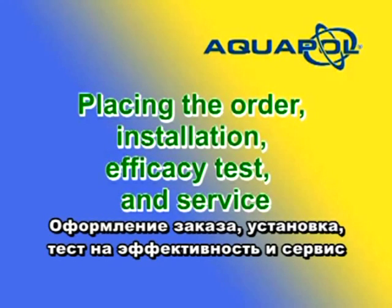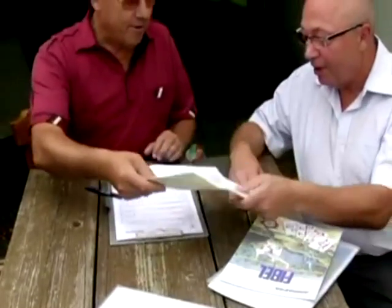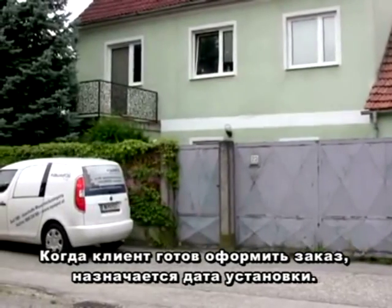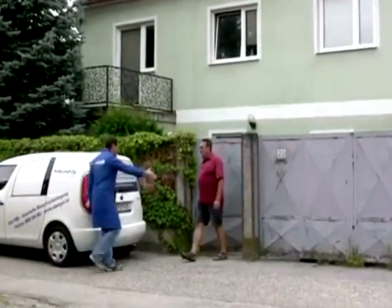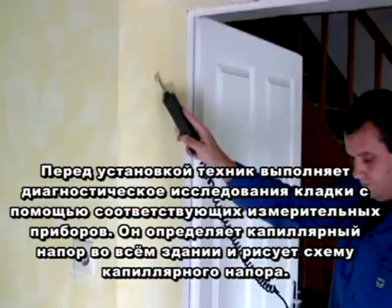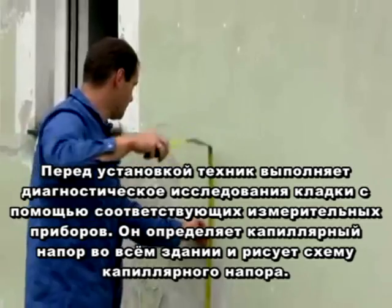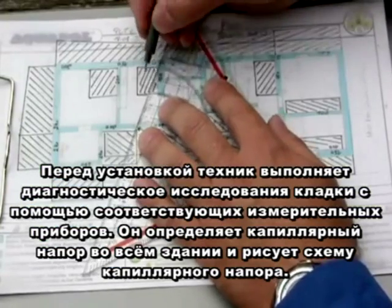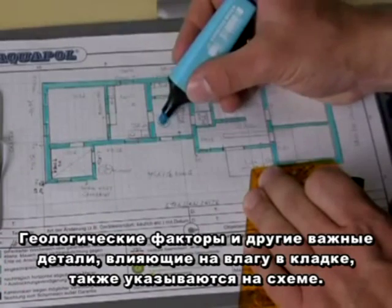Placing the order, installation, efficacy test and service. Once the client agrees to place the order with the salesman, an appointment is made for the installation. Before the installation, the technician performs diagnostic investigations of masonry using the appropriate measuring devices. He determines capillary heads for the entire building and draws a capillary head diagram. Geological influences on masonry moisture and other important details are noted on the plan.